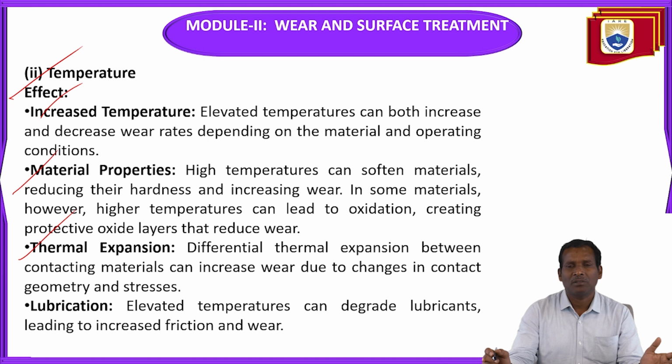So whenever more temperature is present between the contact surfaces, the lubricant will be degraded and it leads to increased friction. Whenever friction increases, wear also automatically increases. In thermal expansion also, the expansion between the contacting materials can increase wear due to the changes of temperature between them.